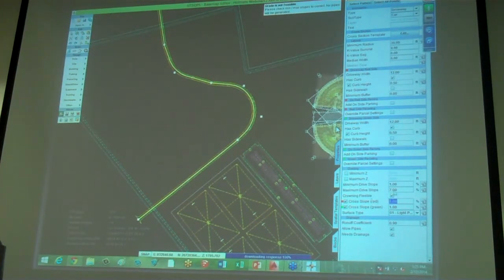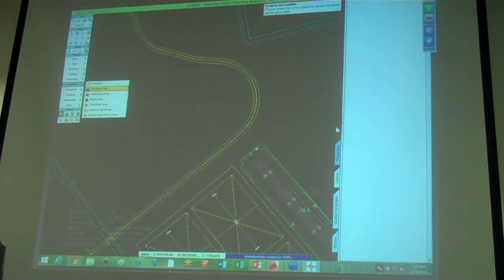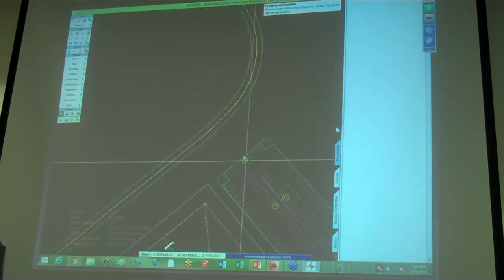You know, I can come in, let's just say, for example, 1 to 7% low right. That's my center line slope. Let's come in with 3.13% if I cross lane, 3.13. I can simply come in and do that. Let's do a quick little tie-in drive. Street, car drive. I can just come off the middle of this point, perpendicular to the roadway. That quick, I'm done with a drive.